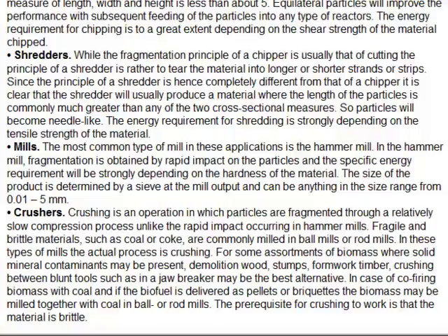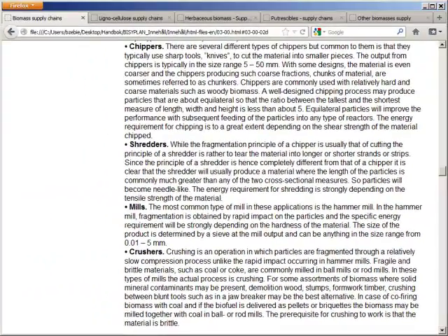In a mill, the material is disintegrated by rapid impact of, for example, hammers or blunt tools, whereas in a crusher the impact is very slow. The material is compressed and breaks under compression. This means that the different types of equipment will have quite different properties, and will be sensitive to different things.